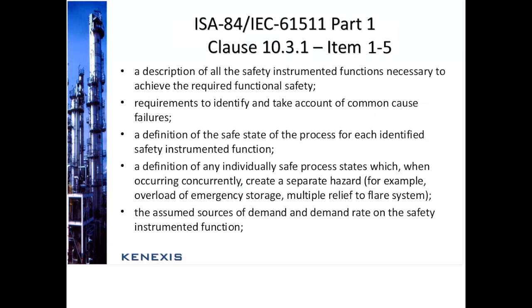So we have a description of all of the safety instrumented functions necessary to achieve the required functional safety. That's a description of the SIFs. That's, for example, high pressure in the fuel gas system causes a shutdown of your fired heater.